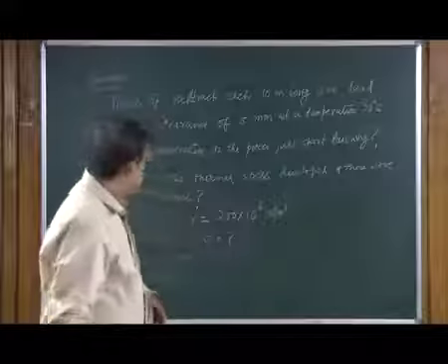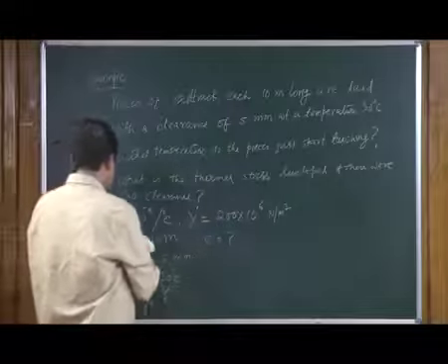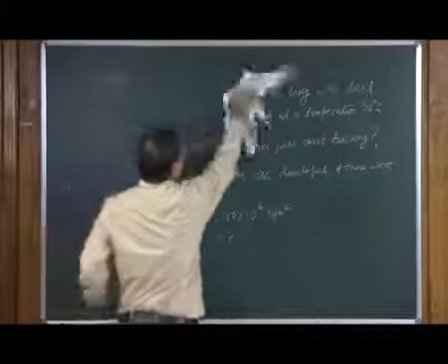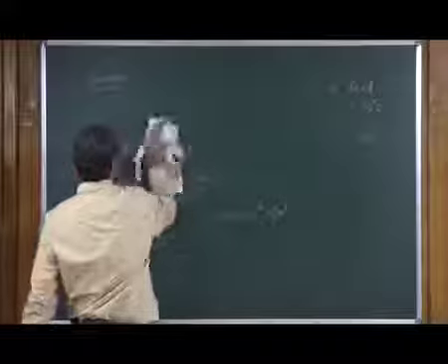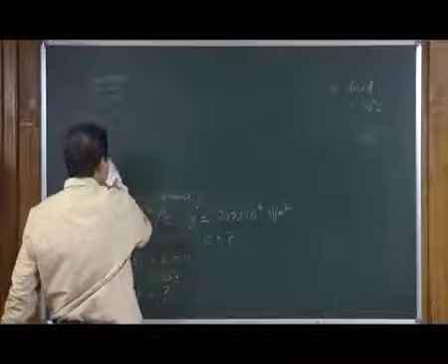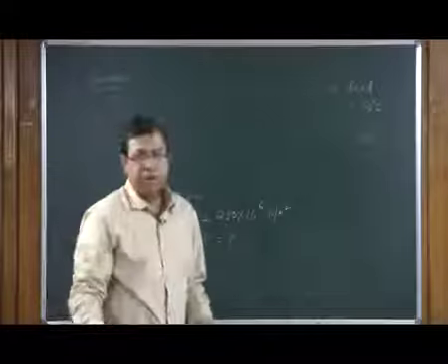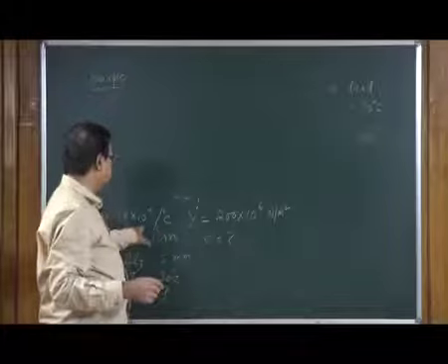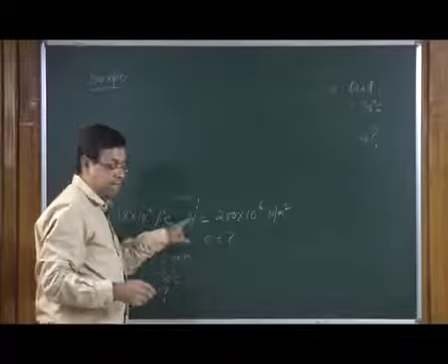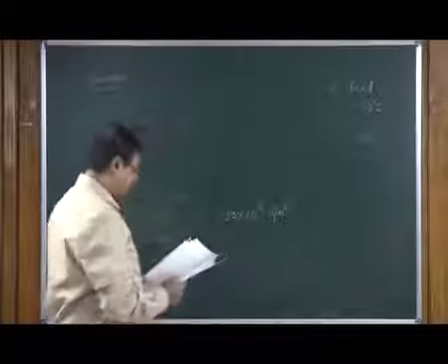And now, let us just try to do this. I am clearing this part of the question. So, now all these quantities that are required to calculate are given here. The linear coefficient of thermal expansion is given as 18 into 10 to the power minus 6 per degree centigrade, and so is the Young's modulus that is given there.